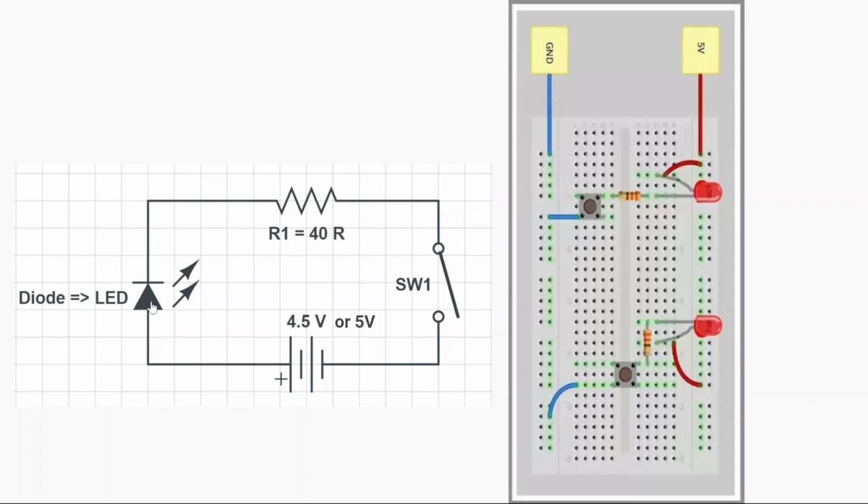Okay. So I connected my LED, I connected the resistor, I connected the switch, and after making all these connections, I want to revisit to make sure that all the connections are fine. So I revisit plus here, negative, the resistor, switch, side 1 and 2, let's say this is 3 and 4, and the other side of the switch is connected to the negative rail. Now, after making sure that my connection is right, I will connect my plus 5, the plus terminal of the battery or the power supply, using this wire here, and the negative side, which is the ground, I will connect here. Once I do that, and if the connections are right as mentioned, then the LED will glow.